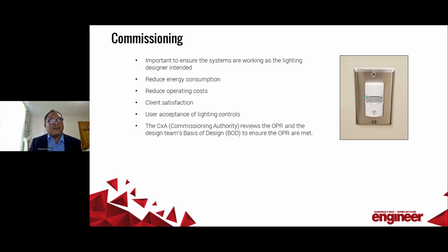And sometimes a wall-mounted occupancy sensor isn't the best location for an occupancy sensor. So doing the commissioning and having a commissioning team, they would be able to catch those particular items during their design reviews. So the commissioning authority, which is abbreviated as CXA, reviews the OPR and design team's basis of design to ensure that the OPR are met.